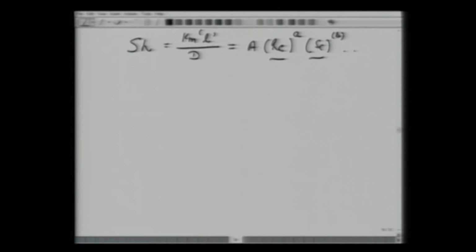Still, we also said that there are some theories, and these theories are used to find out how the mass transfer coefficient may depend upon, say, the diffusion coefficient, etc. So there are three theories. Let's note down these three theories. One is very popular, it's called film theory.